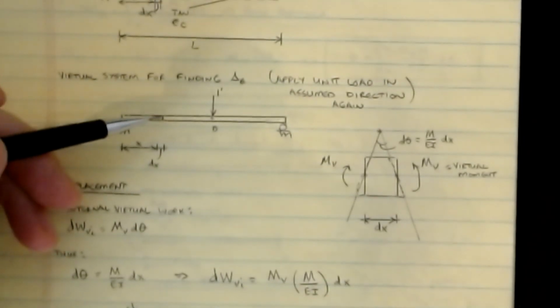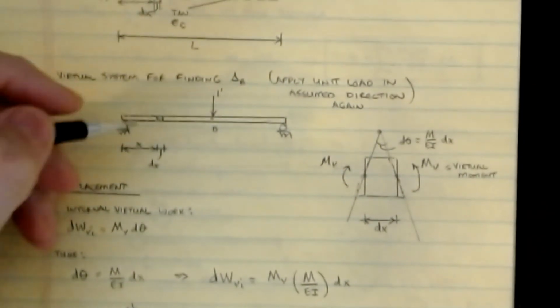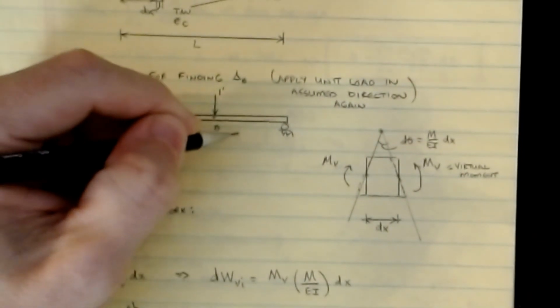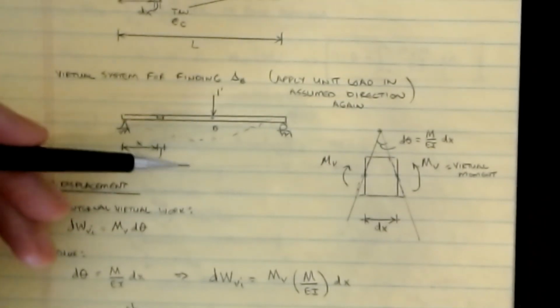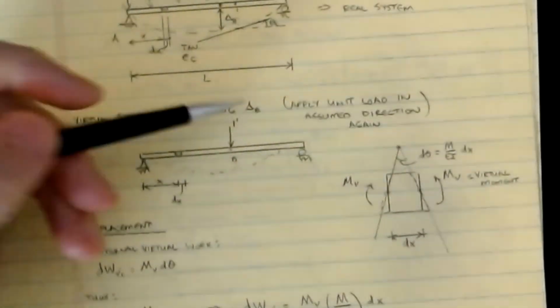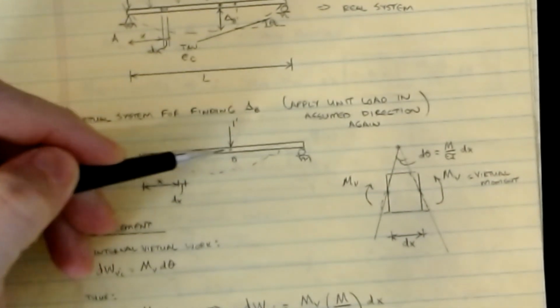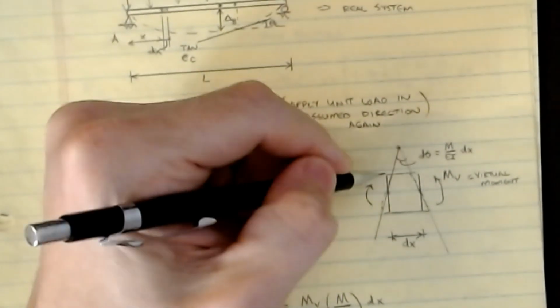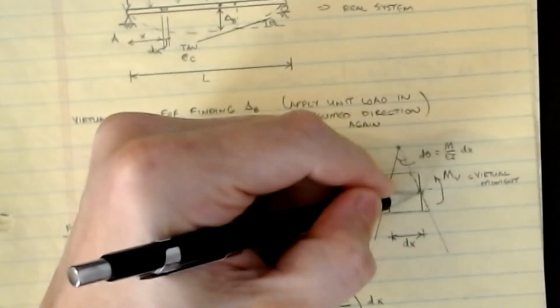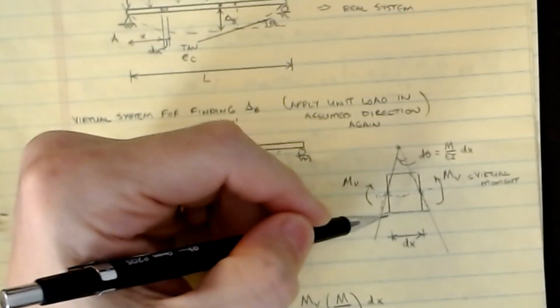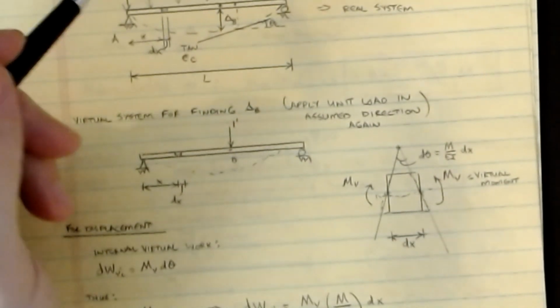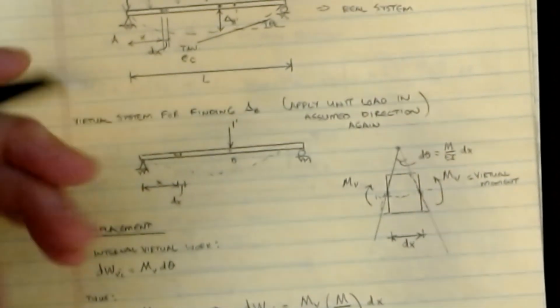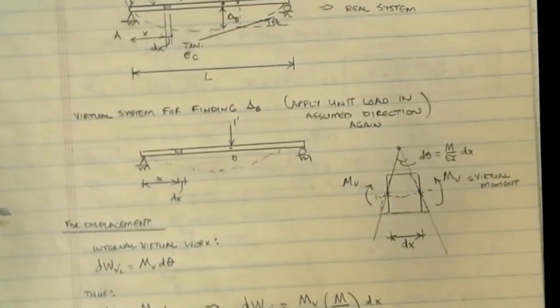So we know from our derivation before that when this beam flexes, we're going to get some sort of deflected shape or elastic curve that bows this thing down, and as a result, this beam element is going to have moments on the end of it. If this element is small enough, for an arbitrary element in here with a 1 kip load, it flexes such that, if we assume a rectangular cross section, this point across here is the neutral axis, and then this represents the strain. The bottom wants to get longer and the top wants to get shorter as we look at the slice of the piece. It turns it from a rectangle slice into kind of a trapezoidal shape.